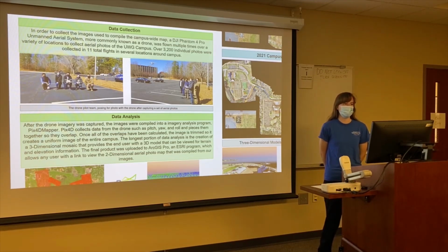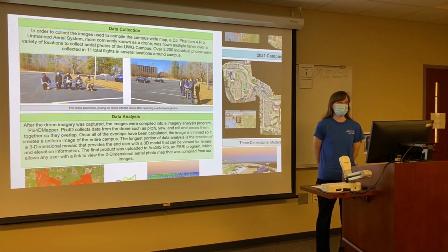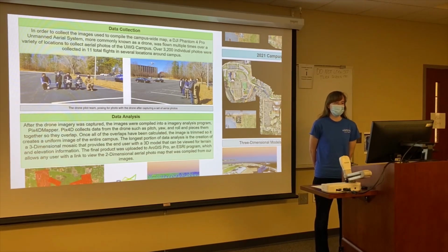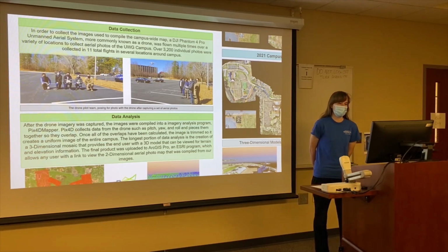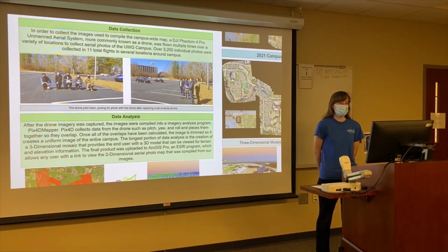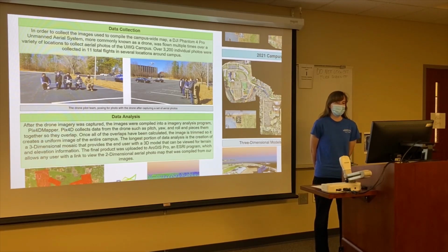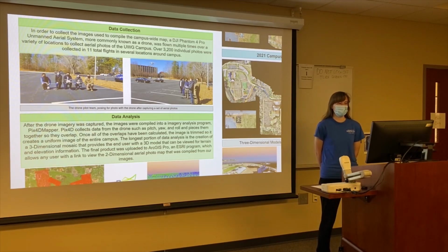Over 3,200 individual photos were collected in 11 total flights in several locations around campus. After the drone imagery was captured, the images were compiled into an imagery analysis program, Pix4D Mapper. Pix4D collects data from the drone, such as pitch, yaw, and roll, and pieces them together so they overlap. Once all of the overlaps have been calculated, the image is trimmed so it creates a uniform image of the